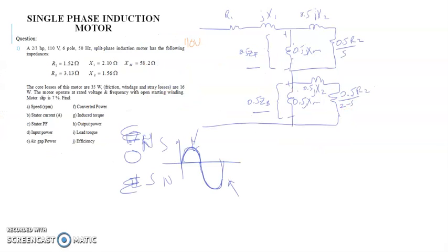Okay, as I mentioned before, from the statement that we have, we transfer into circuit. We draw the circuit, we list down all the parameters, and we list down all the scenario. So the scenario is that we have the system with 110 volts incoming, with a motor rating of 2/3 horsepower. We can convert 1 horsepower equal to 746 watts per horsepower.